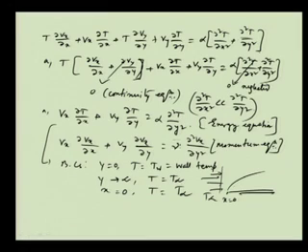So, y tends to infinity means somewhere beyond the boundary layer thickness. This is the idea of T equal to T infinity. So, these are the boundary conditions. Now, this energy equation is also non-dimensionalized with variables, as we have done in the case of the momentum equation.